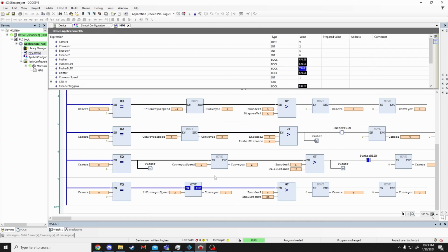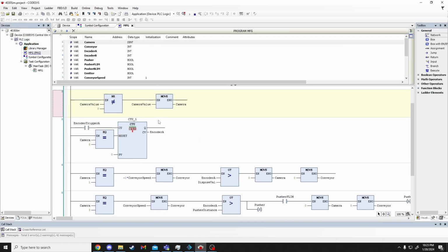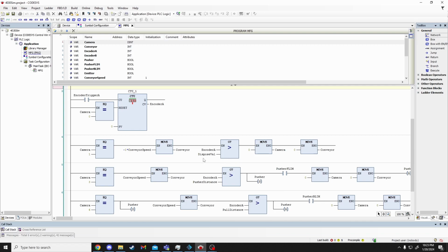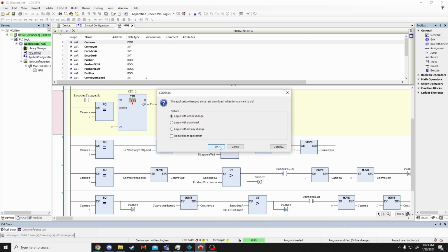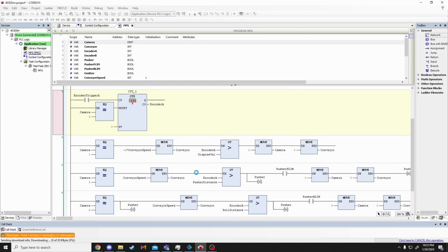I just said that we could probably speed this up. So actually, why don't we go ahead and do this now? What I can do here is take this constant. This is just meant to flip the direction of the conveyor, but we're going to just multiply that by 2, and we'll speed up the scrapping process as well, because that also doesn't need to touch the piston.